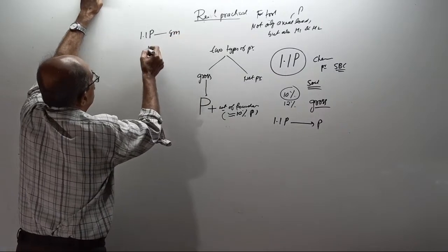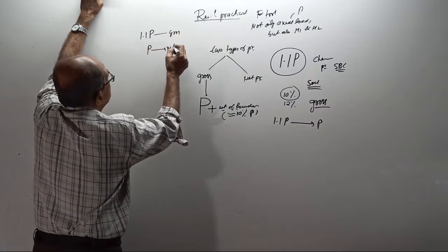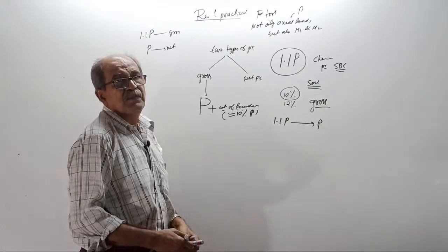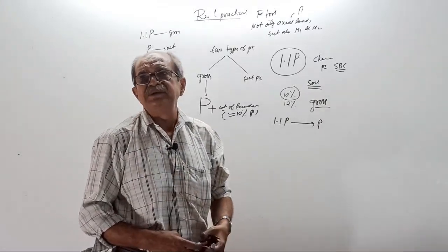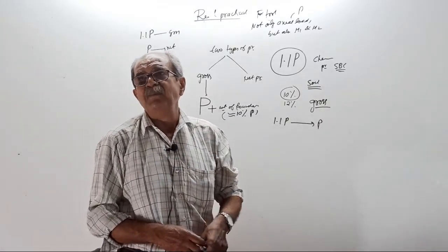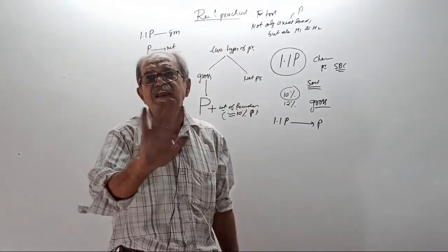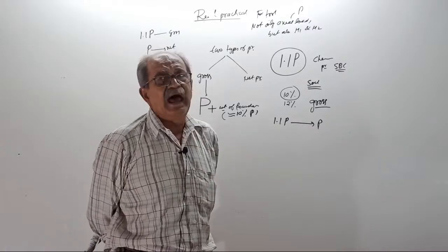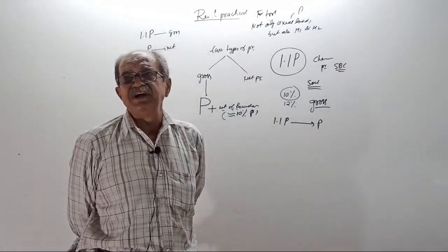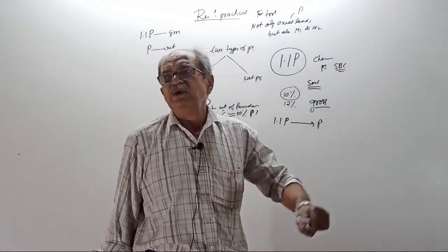Gross. If you write only P, it is net pressure. Remember, but ETABS will always give gross pressure. No problem, it will calculate net pressure. You don't have to tell ETABS. So in the ETABS model, when you go to pressure check and move the cursor, it will give gross pressure.